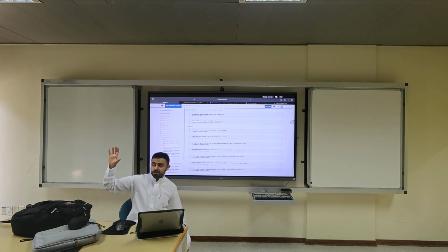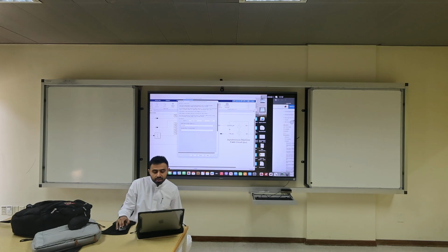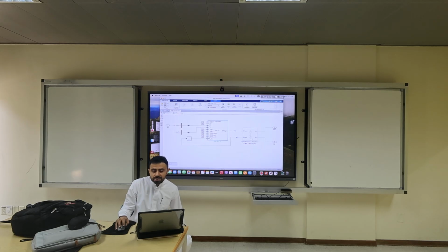The exciter, what is the job of that? So we have AVR. AVR changes EF, right? The exciter, what does it change? Do we have frequency control here? No, not here. The AVR is the automatic voltage control, and the exciter is the excitation circuit itself. I will show you the exciter commands here. If you go back to MATLAB, it goes to the field circuit. The output here, the field command, goes to the excitation circuit.